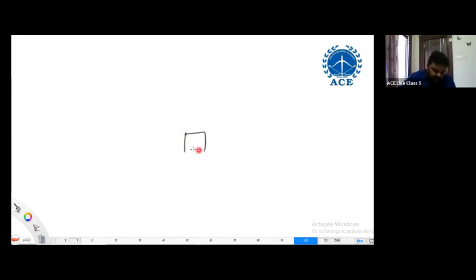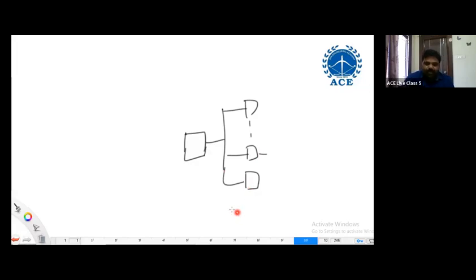Yes, there is a logic gate which is CMOS. Assume that you connect more gates to it. Then load capacitance is the internal capacitance of the devices in this logic gate and also the input capacitance or gate capacitance of each and every MOSFET connected here. That means CL increases when the number of gates at the output increases.